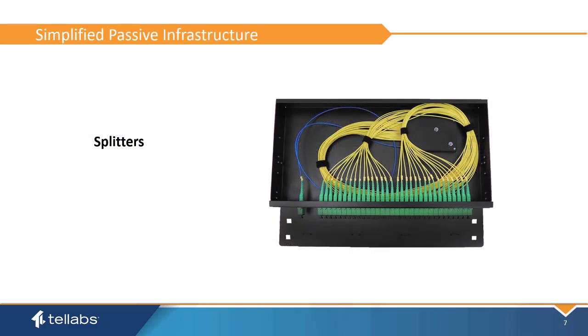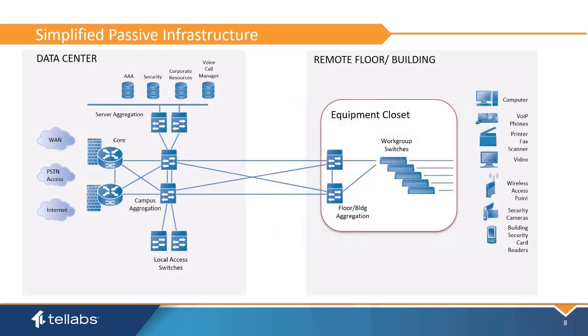Optical LAN relies on passive components like optical splitters, which don't require power or active cooling. This reduces points of failure. This is a clear advantage compared to traditional LAN, which depends on powered switches and other active equipment prone to outages or malfunctions.